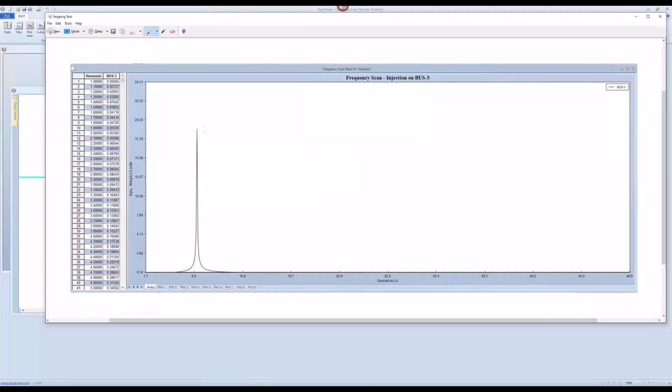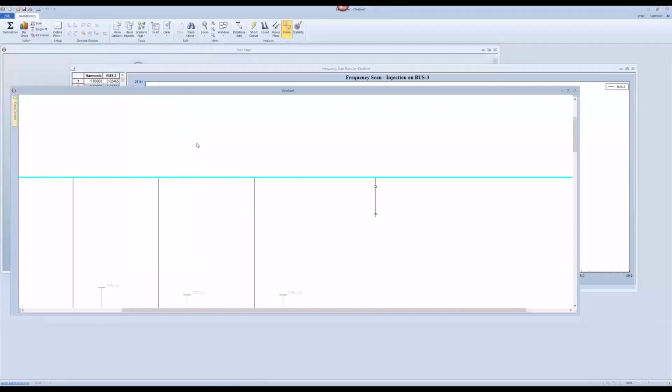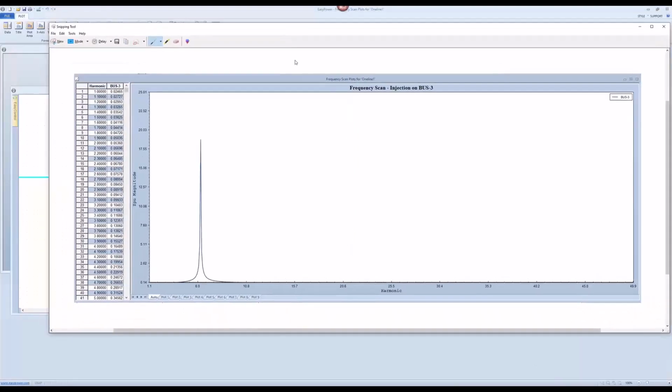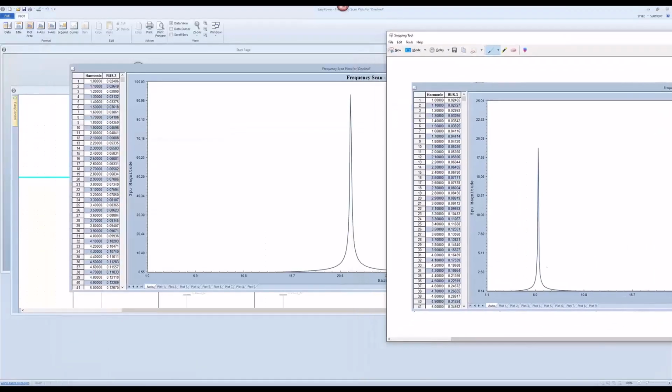Because you insert new capacitance by the new cap bank, right? Remember what we had just now. If I open this one, my resonance point is about the 21st, 22nd harmonic order, right? But after I introduce a new capacitor, I have shifted my resonance point to the 6th or 7th order harmonics, which is a big change of my system frequency response, right? And that actually could introduce more problems at the lower order of the harmonics.